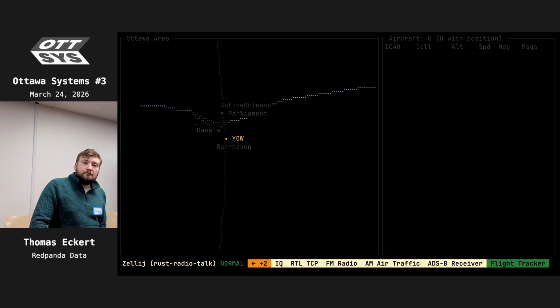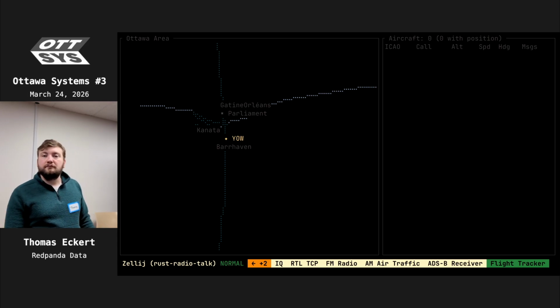There's also what's known as unlicensed, sometimes called ITU bands or ISM bands, where essentially you can use the band without a license as long as you're using a valid transmitter. Cordless phones are the classic example. You don't need a license to operate a cordless phone. It transmits in the 900 megahertz band. You can buy one from Walmart, pick it up, use it. Totally fine, totally safe, allowed to use that.